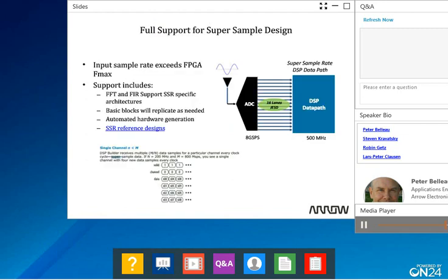The DSP sample rate in your design may exceed the FPGA clock rate, such as in a super sample rate system, for example, in high-speed wireless front-end designs. In a radar or direct RF system with gigahertz digital to analog converters, the signal driving the DAC can have a sample rate in the gigahertz range. This high-speed system requires innovative architectural solutions and support for high-speed parallel processing. The DSP Builder Advanced Blockset Interpolation Filter IP has built-in support for super sample rate signals, and the vector support of its primitive library makes it easy for you to design your super sample rate module.